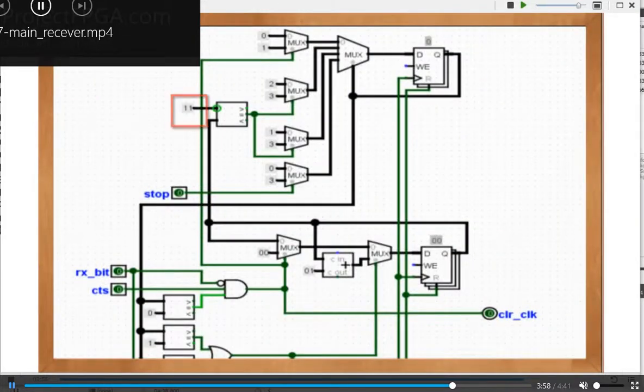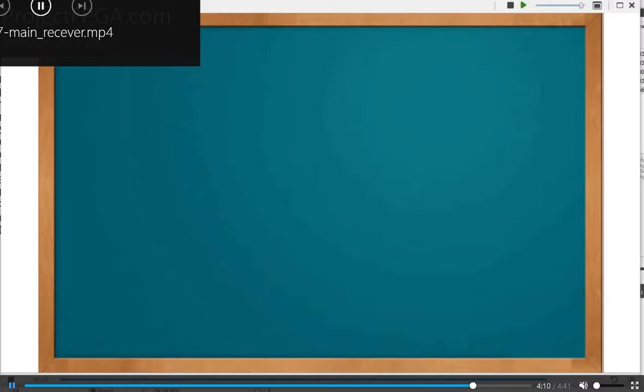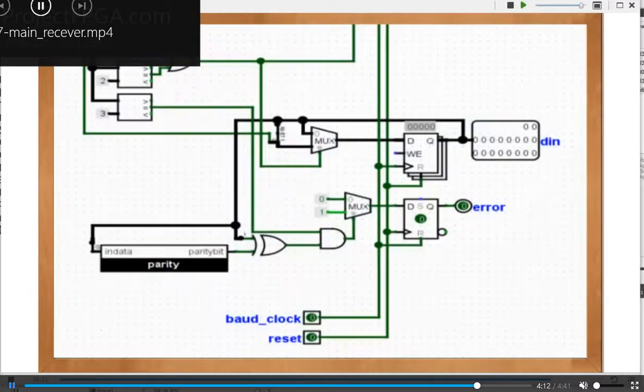And whenever the RS bit count register equals number 11 in hexadecimal or 18 in decimal, then it moves to stage 3. If the stop bit is on at stage 3, everything halts here, else the RX FSM moves to stage 0 and data reception starts afresh. Also, at this stage is when the error bit is calculated. This AND gate enables the generated error to trigger at this stage.